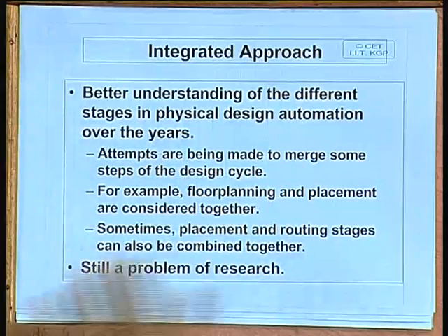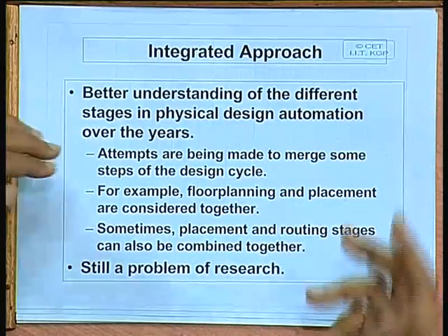Okay. So we have talked about some algorithms related to floor planning and pin assignments, and subsequently we have other steps, first of course placement, then routing. But we will see that in many situations we may have to go for an integrated approach. This again depends on the design style. For example, in the standard cell approach I told you that pin assignment and routing can go together.